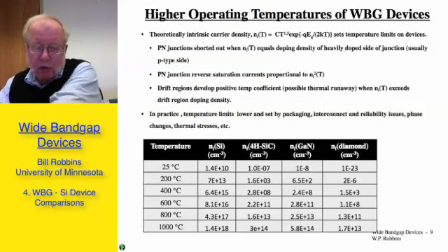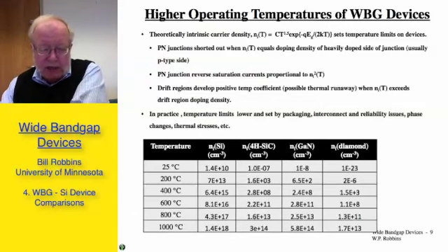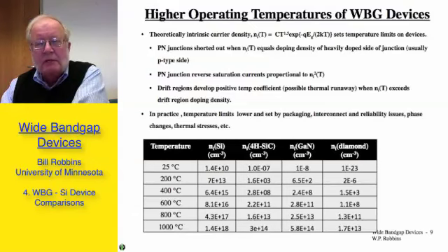And so at the typical doping densities that we use, our intrinsic carrier densities for these wide bandgap materials are well below the typical doping densities even in the lightly doped drift region. Whereas in silicon at this 600 degrees centigrade, we're a couple orders of magnitude higher in intrinsic carrier density than what a drift region for a high voltage device would be doped at.